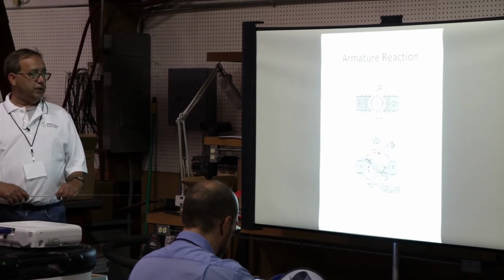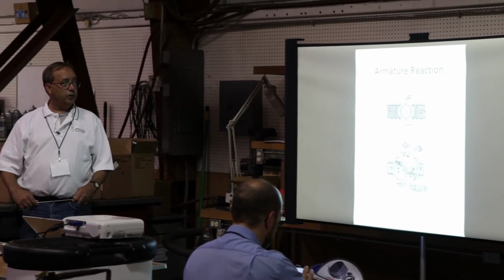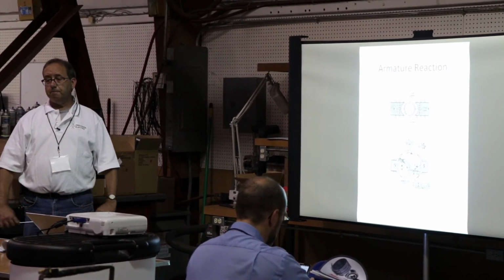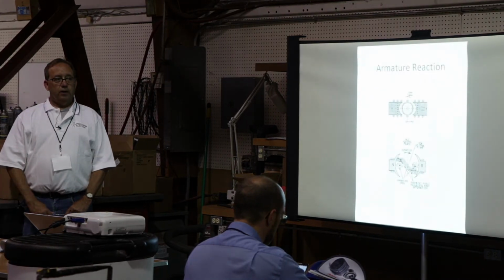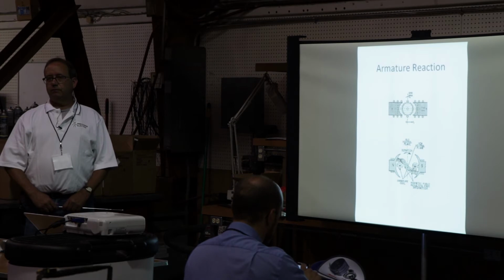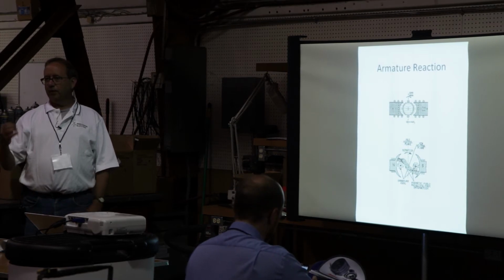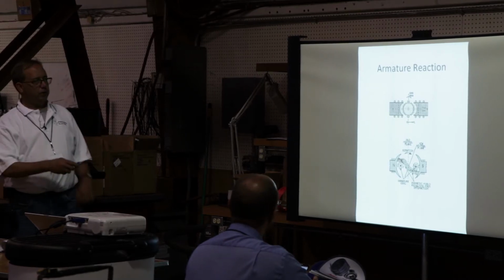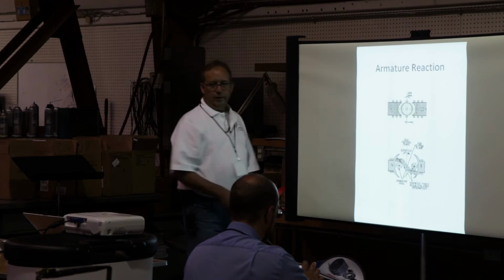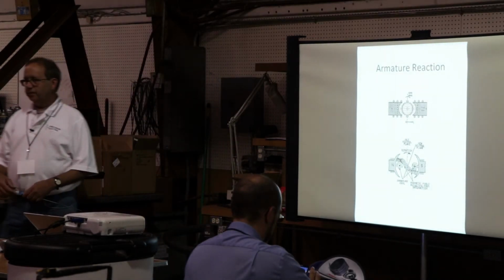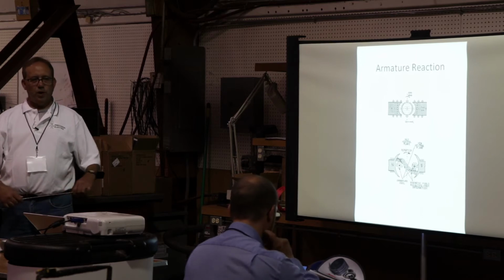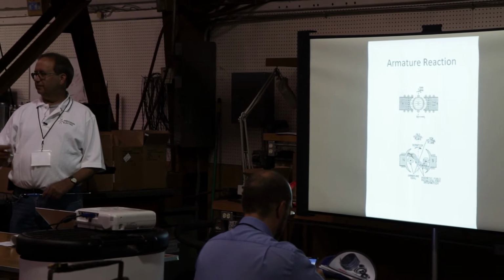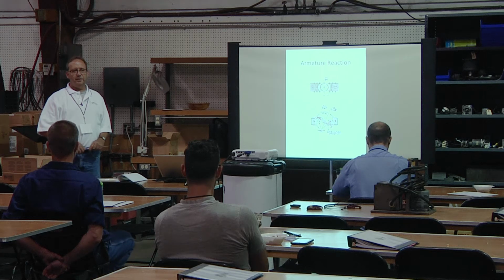This is an illustration of a phenomenon called armature reaction, and we'll explain the reason for interpoles. You guys all got power tools that run off of AC or DC or whatever. They got that little universal motor in them. You've all taken them apart probably, and you just see two poles and a couple brushes, and they go like a bat out of hell. They're little series motors, but they almost always spark. They almost always are sparking at the comm.